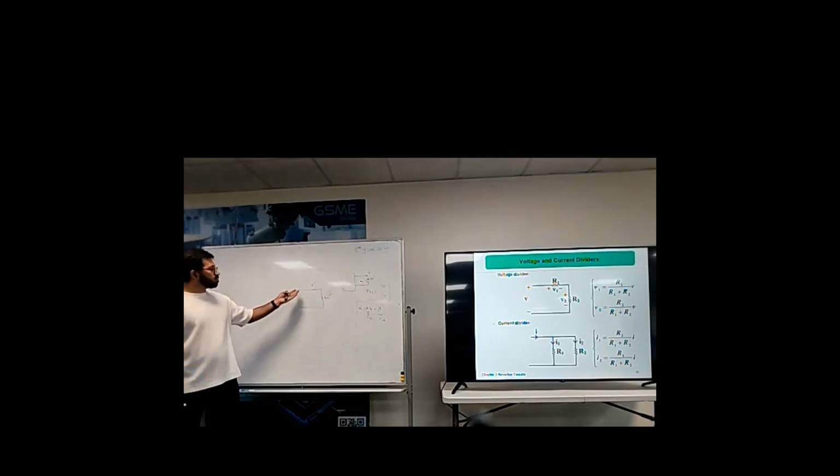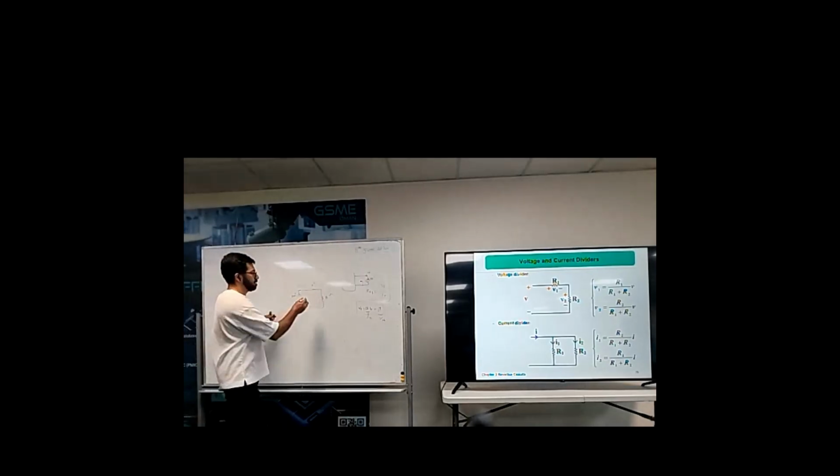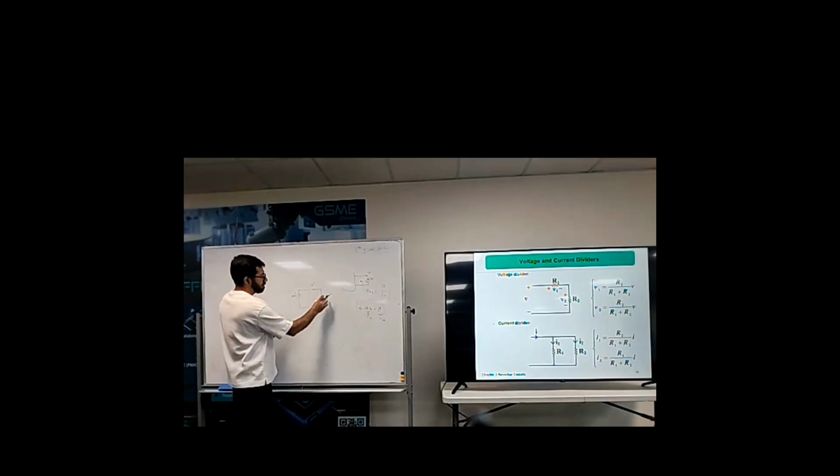If I apply 100 volt to these two series resistors, how much is the voltage? Let me consider this 9. How much is the voltage of this resistor? Yeah, we can easily use the voltage divider. That's the value of this resistor over the sum of the resistors multiplied by the voltage source.